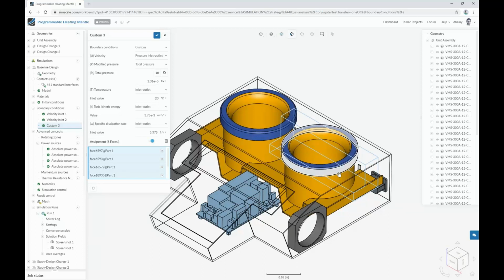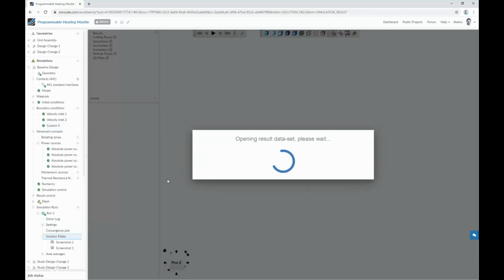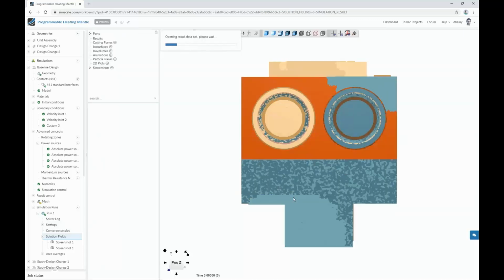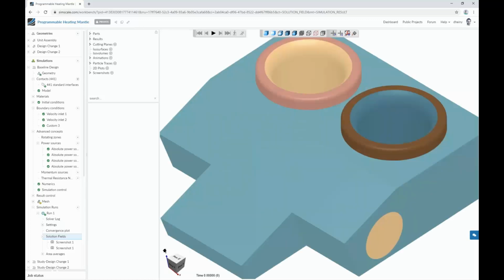And I guess where we now are in the design process is we have an initial strategy of how to remove this heat, of how to design the thermal management of this assembly, and now SimScale allows us to actually validate whether or not this makes sense, right? Whether or not this will actually work. And so this analysis is pre-run. I think we're looking at 4 million cells, something like that. So that took about 90 minutes ish to compute. And now we're going to look at results.